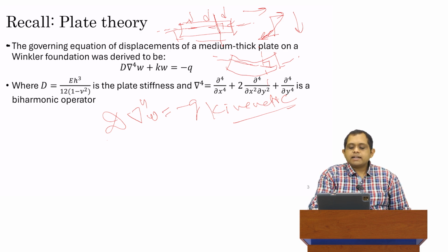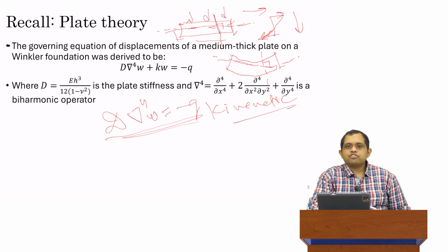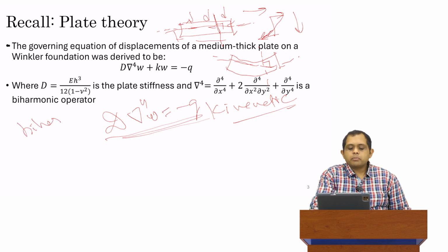And what we ultimately get is this equation, which is the Sophie-Germain equation. It tells us that if we apply an external transverse load q, then our displacement in this plate is going to be related to a fourth order equation, which sometimes we also call the biharmonic equation.